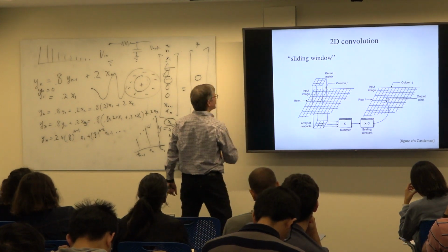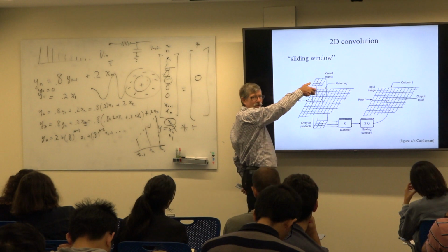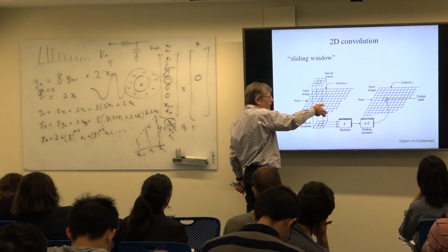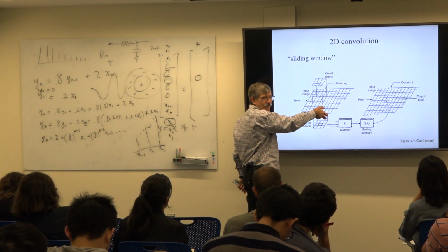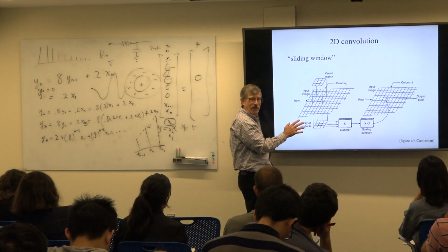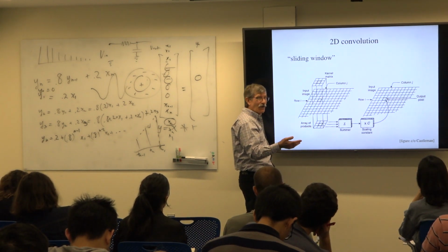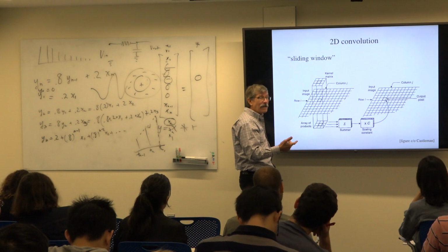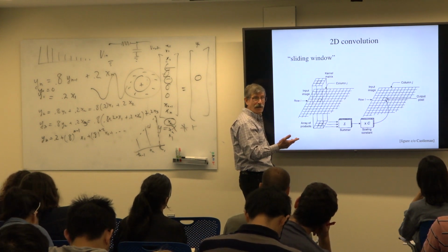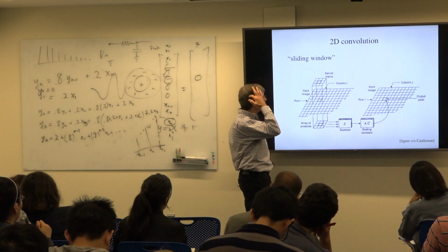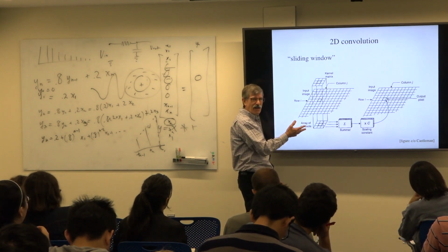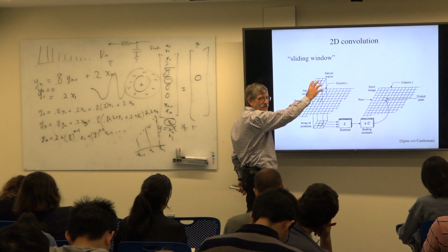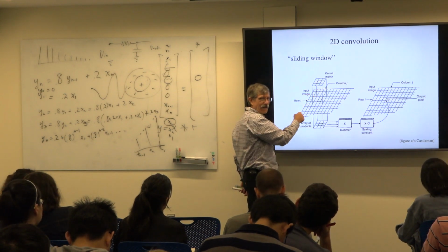So convolution again is take the impulse response and flip it around, and then do dot products everywhere. Okay, but the dot product now is put that 3 by 3 on top of the 3 by 3 pixels, multiply and add. Okay, so we're not going to do the 2D version here, and you can do it in 3, and you can do it in 4, and anytime you're analyzing fMRI data, you're doing it in 4, right? You've got x, y, z, because it's a 3-dimensional image, and you've got time, we've got multiple scans, and so you can talk about filtering your data with a kernel, an impulse response flipped around, a kernel it's called sometimes, that has x and y and maybe z and maybe time.